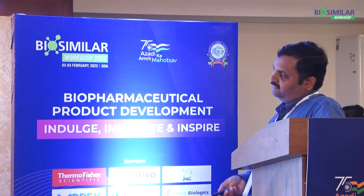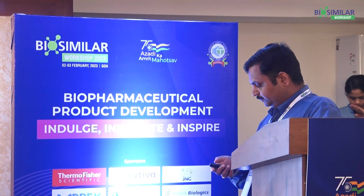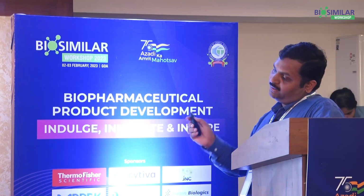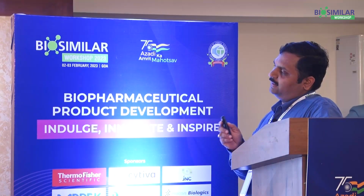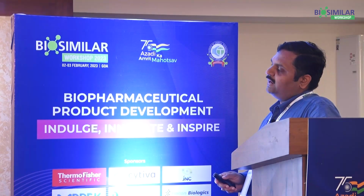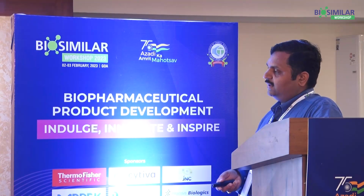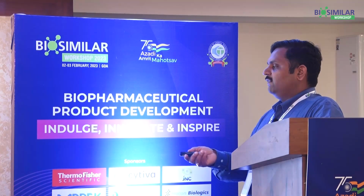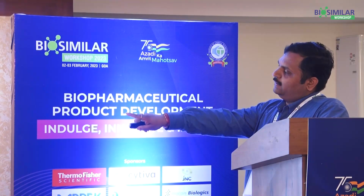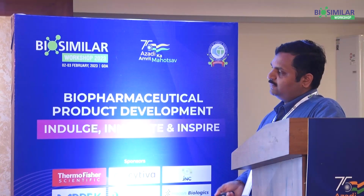Now, in the same regime, in a continuous process, what happens if we collect the breakthrough from the first column onto the second column? We can increase the utilization of the resin capacity. So rather than 10% breakthrough, if we target, let's say, 70, the first column will be completely loaded, as you can see in the second figure, and the breakthrough can be collected on the second column. This is how we can utilize the capacity of both columns.